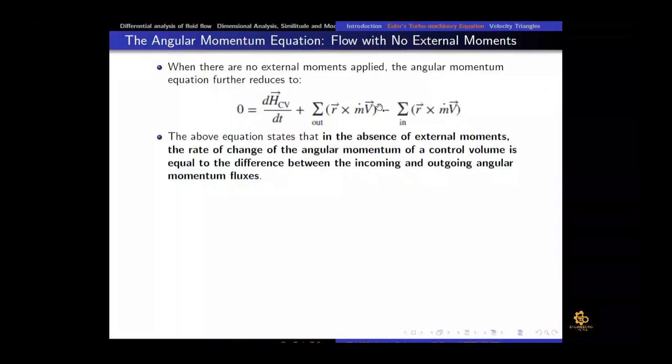When would it be the case? When we have got turbine work, because in this case the left hand side is equal to 0, so we need to move these two terms to the left hand side. So we can say that the angular momentum coming into that control volume and the angular momentum going out, that is positive. It means that the body has gained momentum, right? So that is the case of a turbine, when the blades speed up due to the flow striking on the blades, right?